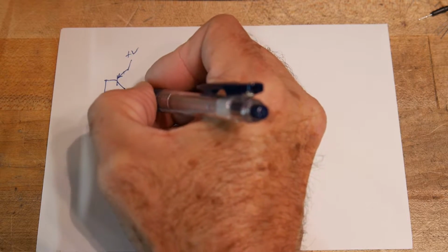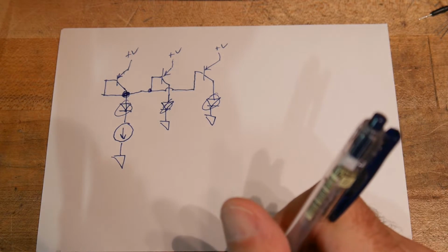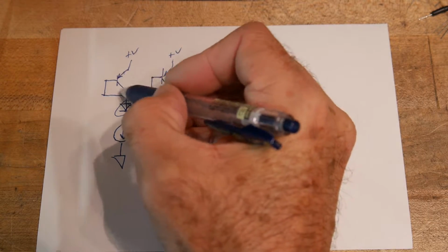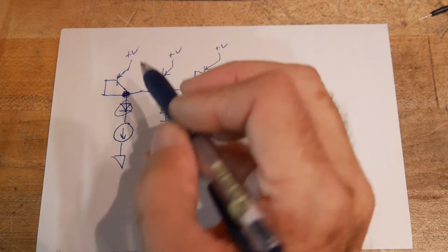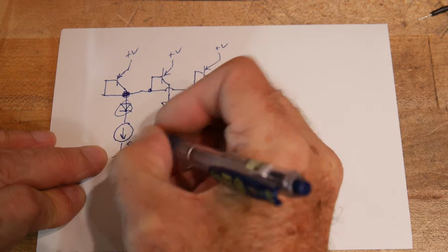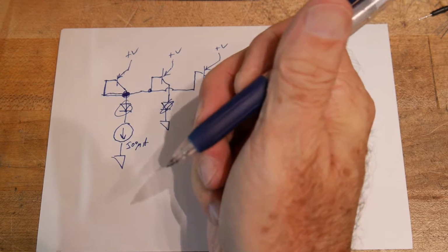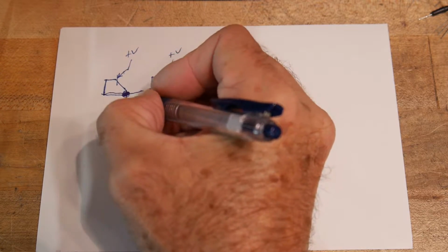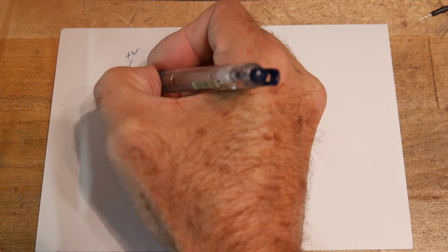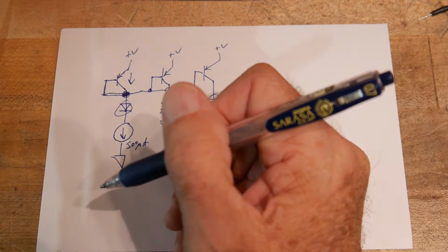If I take this base and I actually short it out to this collector, this thing will act like a current mirror, strangely enough. So whatever current goes through this will get mirrored. So this is already creating a current. We're creating 500 microamps. All right. Now, by connecting the base to the collector, that turns this transistor on no matter what. There's always a way for the electricity to flow, so it can go either way. And it will start to conduct, but it will only conduct up to 500 microamps because we have a constant current in this leg here.